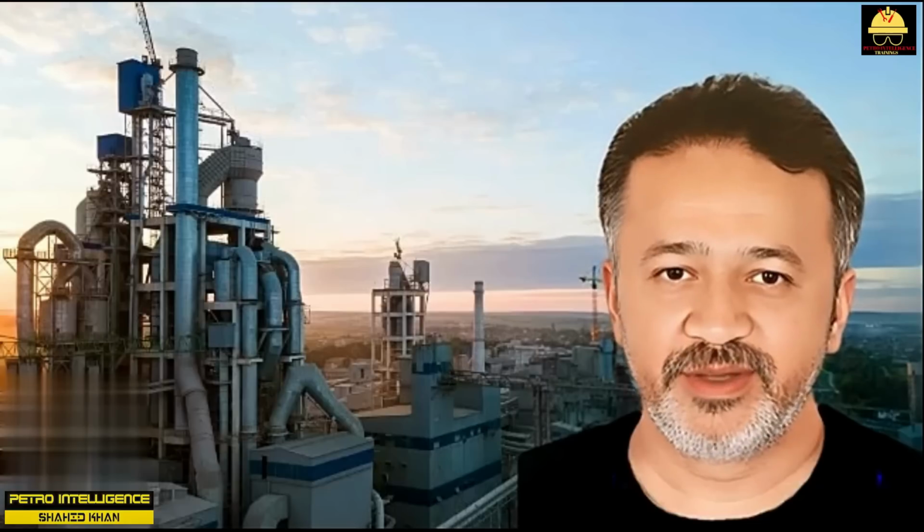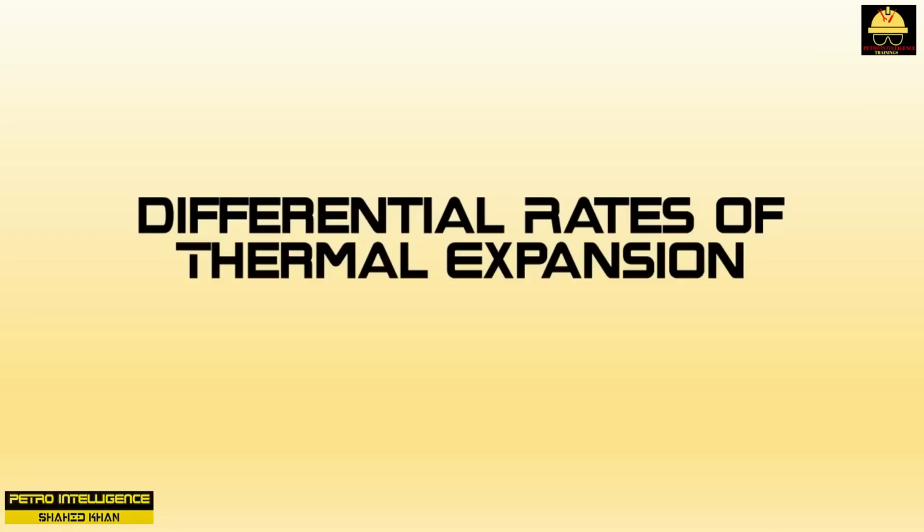To summarize, some of the tubes in the bundle continue to foul until they plug off. These tubes get hotter until they reach the temperature of the hot oil circulating through the shell. Other tubes continue to receive more and more flow. The velocity in these tubes increases to the point where the rate of fouling becomes inconsequential. This velocity is called the terminal tube velocity. These tubes may run 50 to 150 degrees Fahrenheit cooler than the plugged tubes.